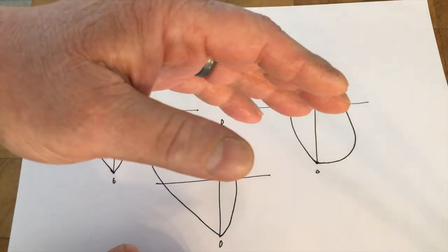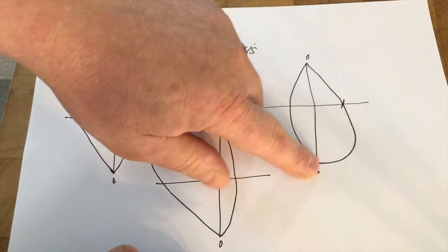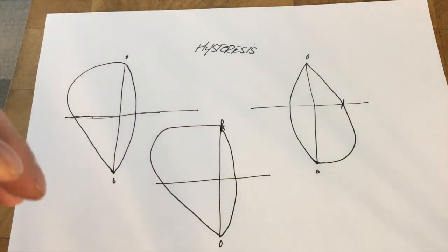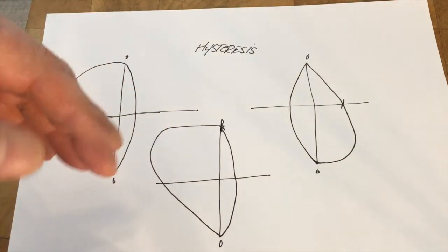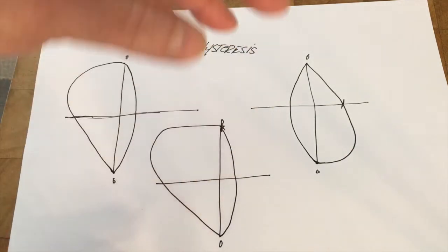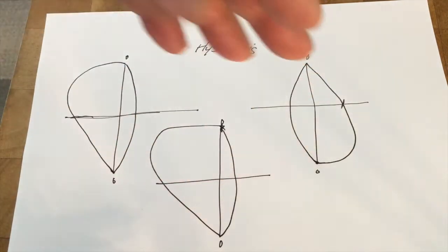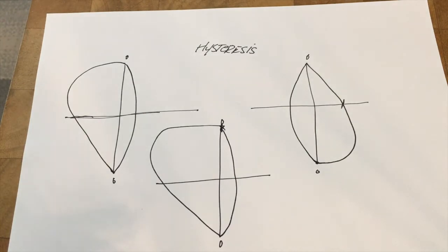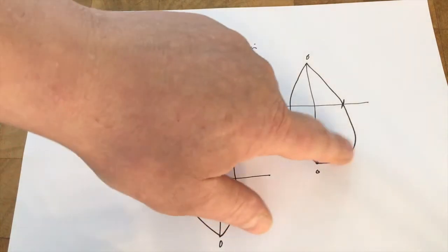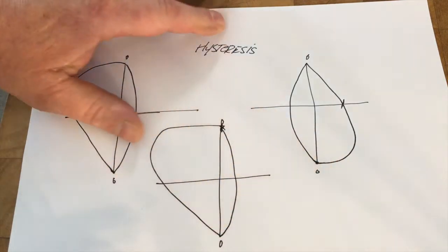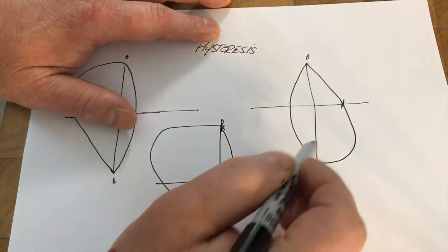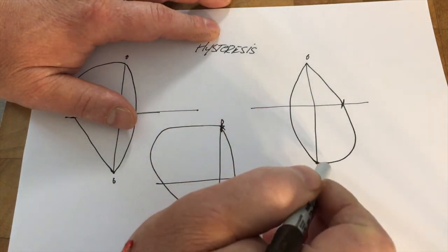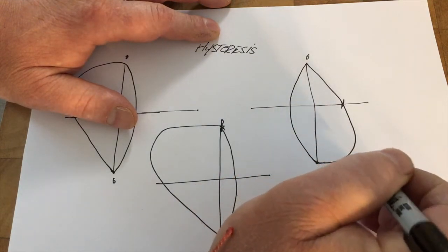So you would think those valves would start closing and it would close at the same rate. But what happens is the hydraulic locking and how the oil gets through there, a lot of times it's the hose system, or the reason that they went to the piggyback is to eliminate a lot of the hysteresis. And how the adjuster is on the compression side a lot of times will provide a lot of hysteresis. But what it is, the shock will open as normally, and then right down here as the shock starts to close, it retains a lot of pressure.